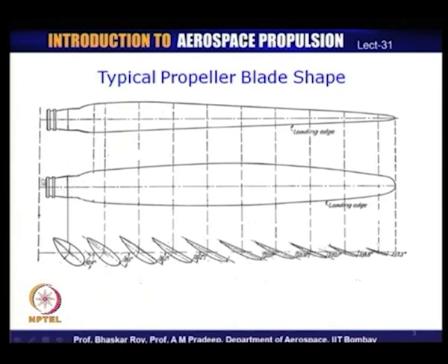So, this portion needs to be made very strong, so that they can hold the propeller in rotation. This is something which has to be taken care of right in the beginning of the design, and as a result, in this portion of the blade, the aerodynamics is often sacrificed and the structural strength of the propeller blade at the root is given precedence.